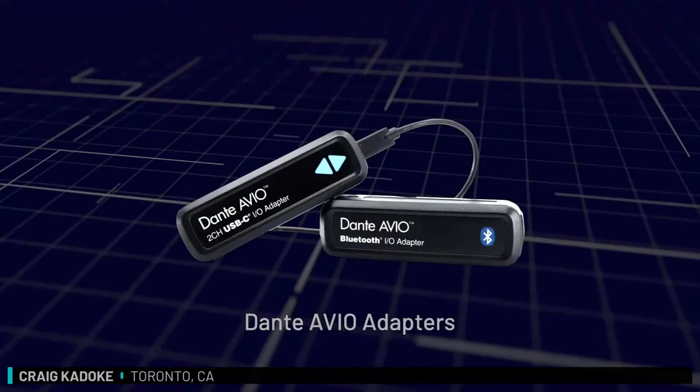DVS is very functional when it's on a full Dante network, but having the adapters is a much better way to deal with a number of situations, especially with the licensing of DVS and the fact that it's all a name-based relational patch. If you have to swap out a computer mid-show, if it's a dongle, it just swaps naturally. If it's DVS going from one machine to another, you're going to have to repatch everything.